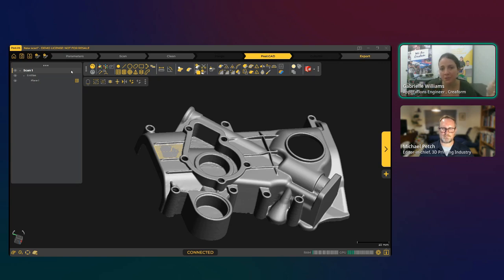And you also want to make sure that you're scanning with the shortest path, if that makes sense. I have a little slide that I can show on it. When you're scanning, you want to make sure you're taking the shortest path from one point to another. So for example, if I'm scanning a car door, I don't want to start on the bottom edge of the car door and then go all the way around to the other side and finish. Here, this is perfect.